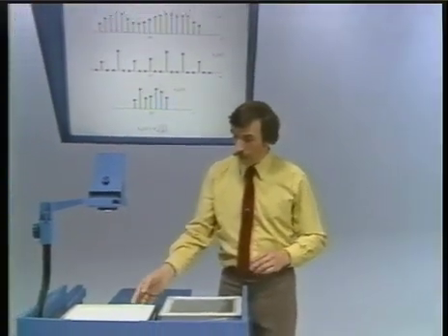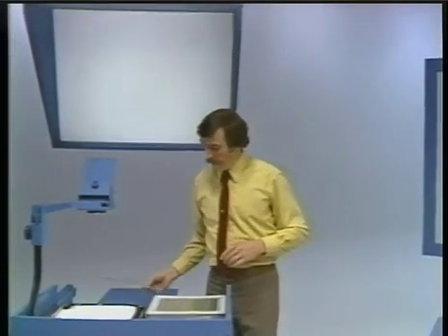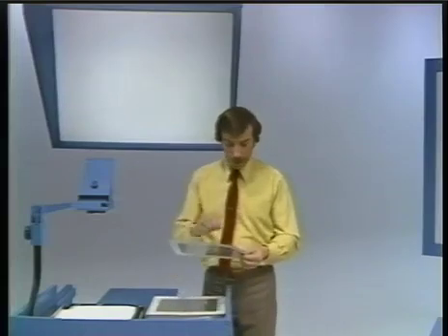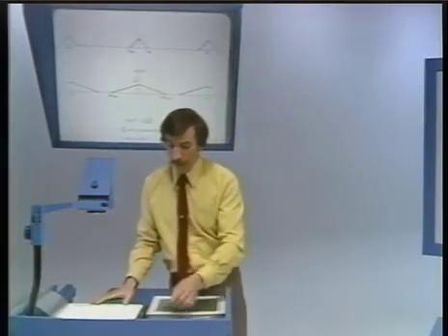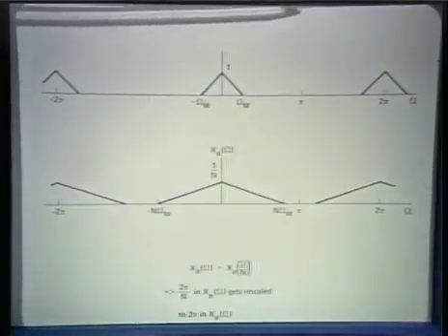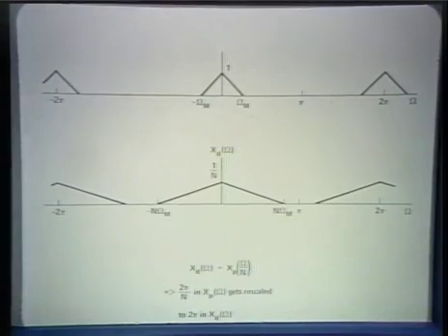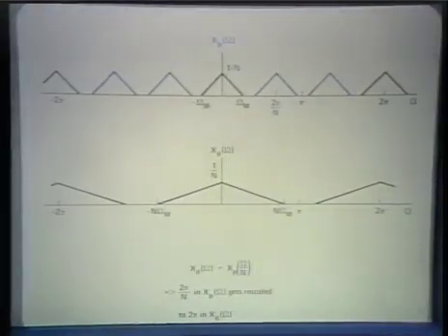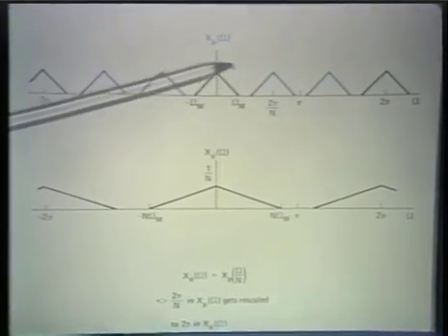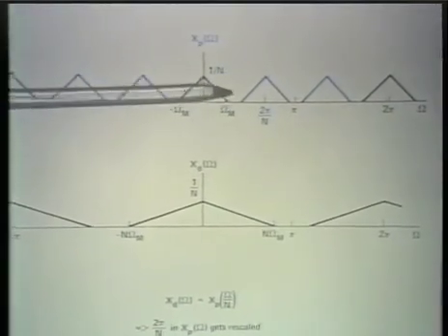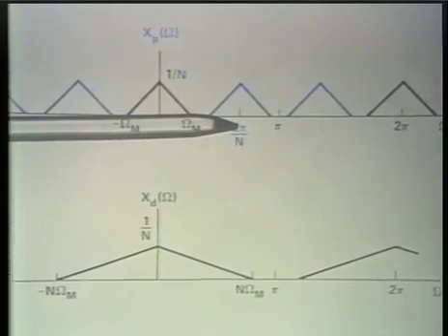So now that we've looked in the time domain in this particular view graph, we now want to look in the frequency domain. And in the frequency domain, we have, again, the Fourier transform of the original sequence, and we have the Fourier transform of the sampled sequence. And now the Fourier transform of the decimated sequence is simply this spectrum with a linear frequency scaling.